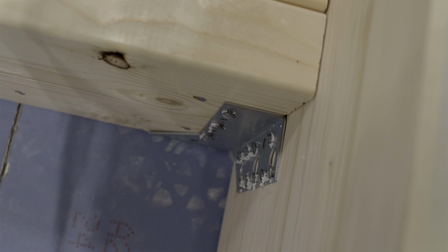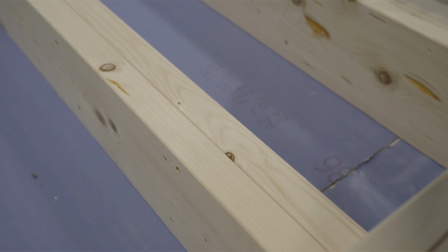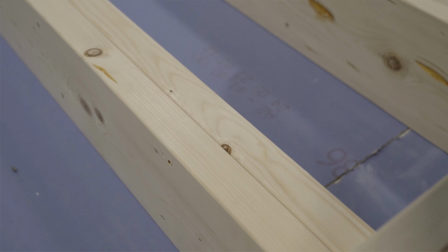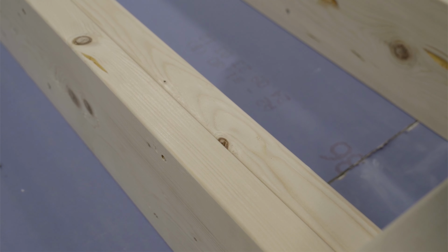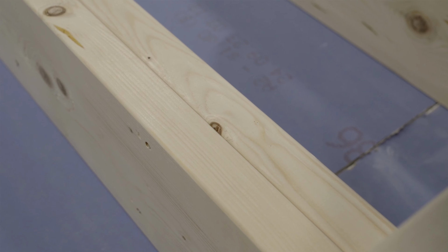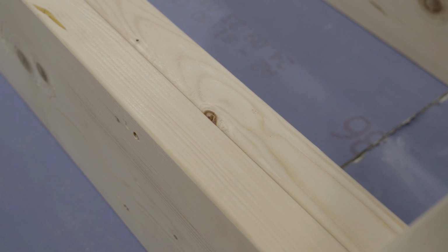In cases of larger loads, beam shoes can also be used. If there is a need for a stiffer structure, double wooden beams, custom-sized glued laminated beams, laminated veneer lumber or engineered wood, or steel beams can be used, especially for large openings.